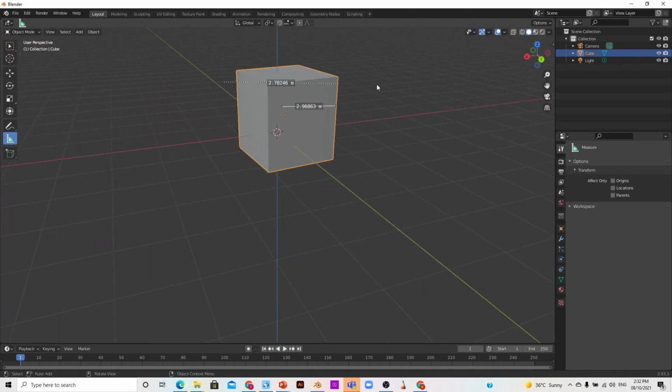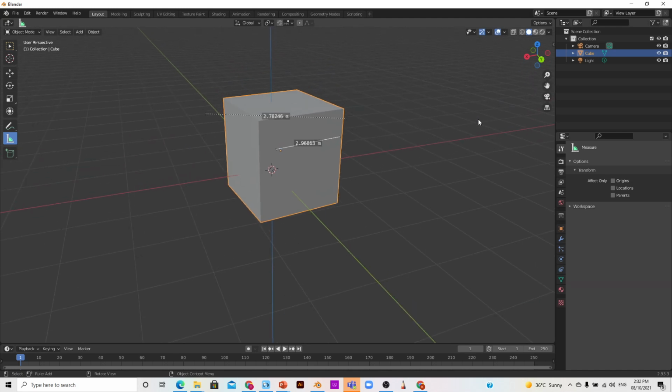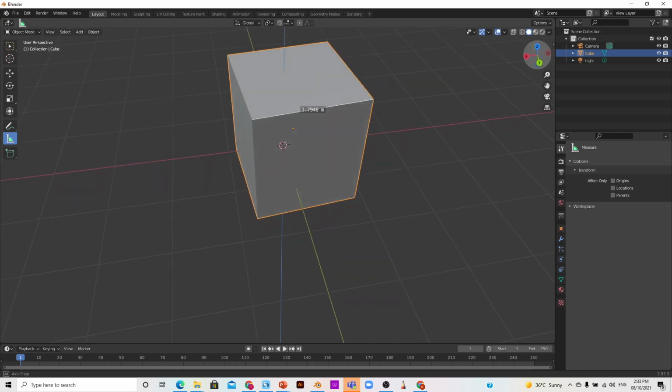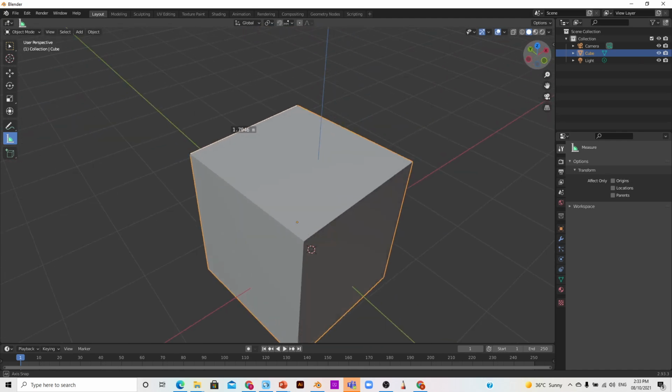Now what is snap tool? I will show you. Wait, press and hold Control and then Z, undo the action. Now first press and hold Control, okay, and then you will activate the snap tool. You see this white color axis, it's the snap tool. Okay, and then press and hold the left key of your mouse to start to measure the object. And now I will release the left key of your mouse, and that's it. Now what you are seeing is the actual measurement of your object.